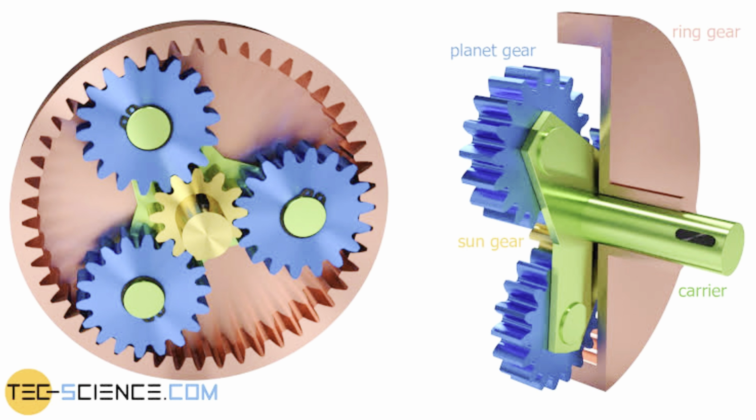The basic planetary gear set consists of a sun gear, ring gear, and 2 or more planet gears, all remaining in constant mesh. The planet gears are connected to each other through a common carrier, which allows the gears to spin on shafts called pinions, which are attached to the carrier.